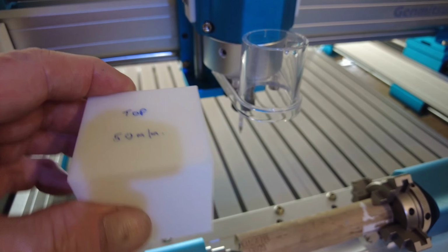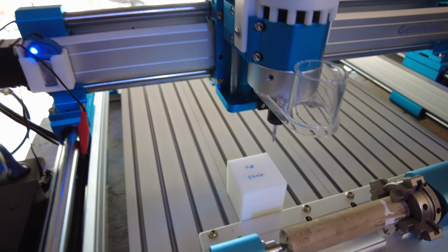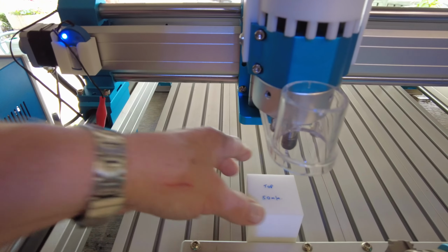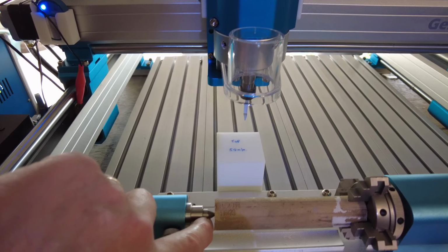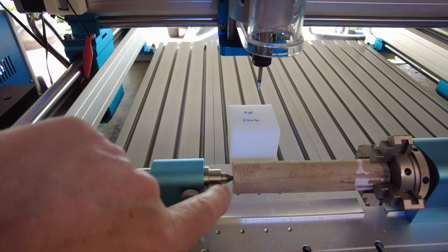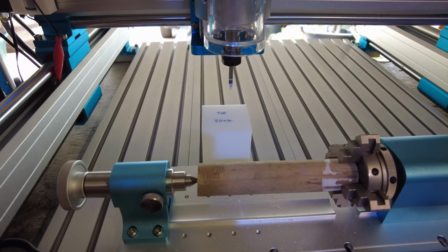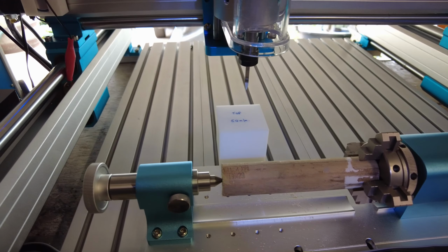And what I do is, that's marked on, I put that on the top, and then I use the touch off probe underneath it, and then that is set correctly from the point of centre that it pivots down here, because that point of centre is exactly 50mm from this table. So when that touches off, that's set correctly.